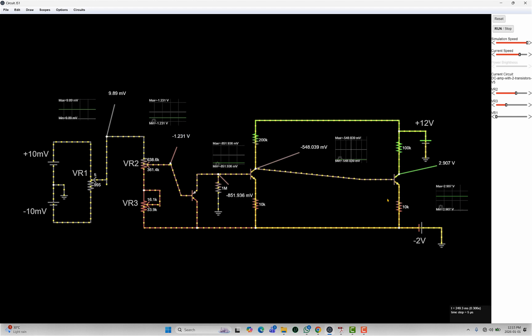You should learn how to use the software. It doesn't take long, maybe just a few hours, and you'll be up and running and it'll save you a lot of time because I don't have to pull out resistors. I don't have to monkey around with batteries or voltage sources. I can just change it on the fly. Like you can edit these just by right clicking, edit.